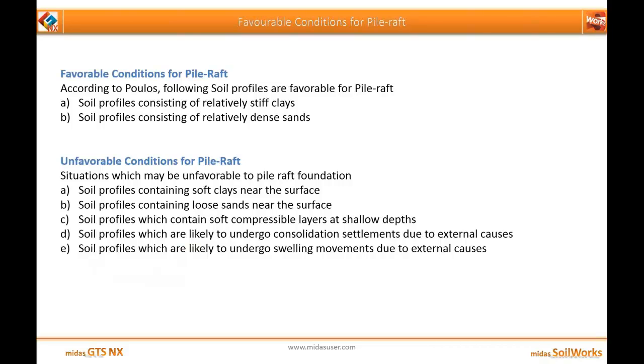Now what are the favorable conditions for pile raft? According to Poulos, wherever the soil profile consists of relatively stiff clays or relatively dense sand, it is a very favorable condition for pile raft. Why so? Because the raft has a very high bearing capacity in that case and provides proper stiffness to the foundation. So the piles just act as a support which enhances the overall function of the raft foundation.